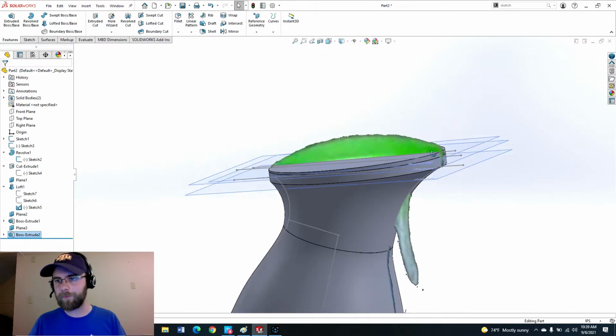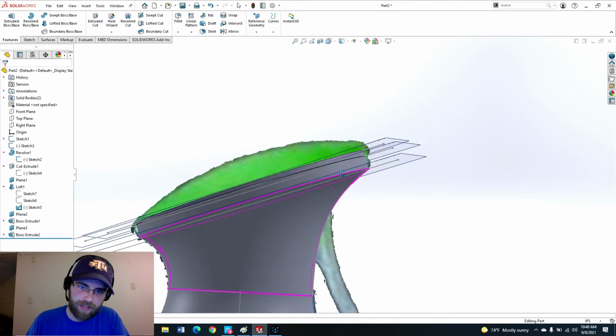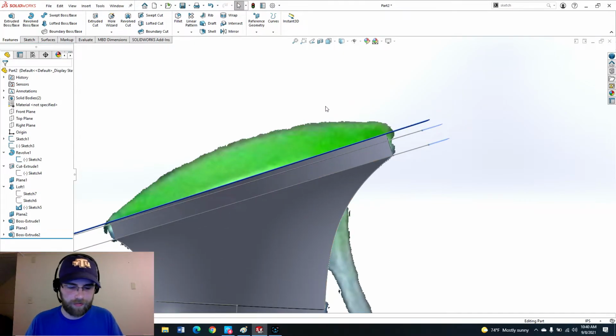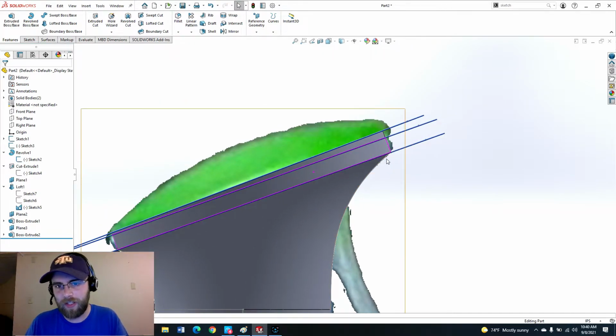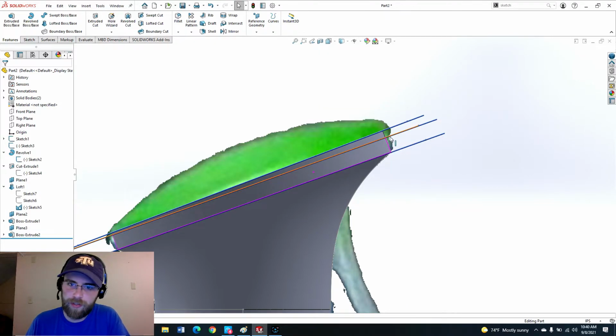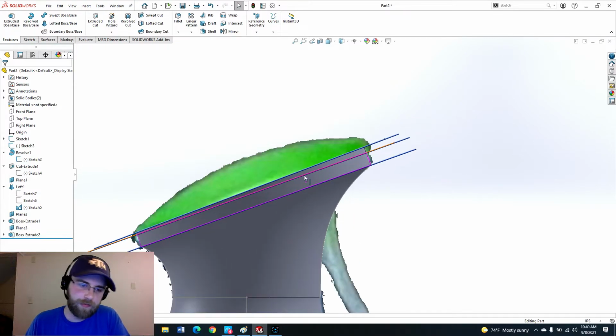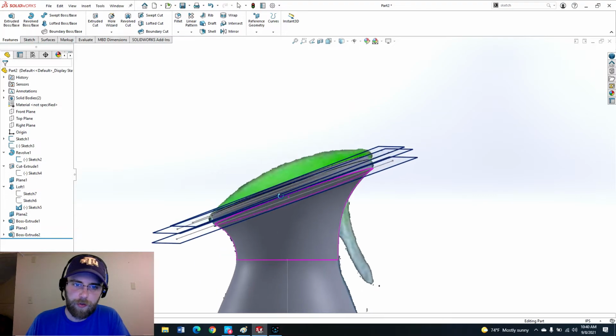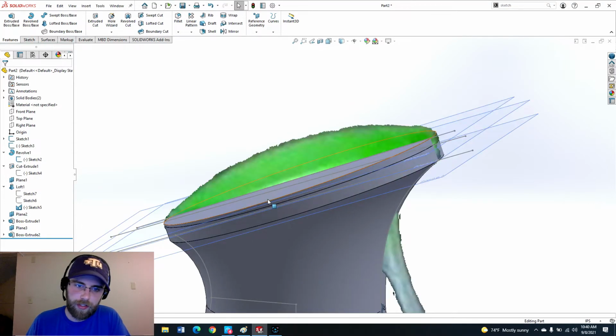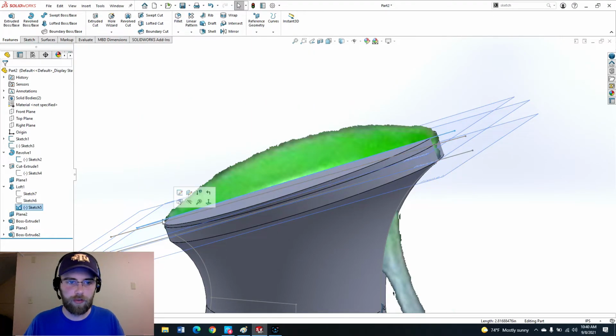So, OK. You'll notice it doesn't completely line up with the picture, and that's just sort of how I drew my guide curve. If I wanted to, I could create a longer oval on this next plane, and instead of extruding up, I could loft up. But really, it's close enough for what I'm wanting to accomplish here. So all that's left at this point is just the dome here on top. And SolidWorks makes that really easy. Instead of having to do some crazy surfacing work, we just have a dome command.